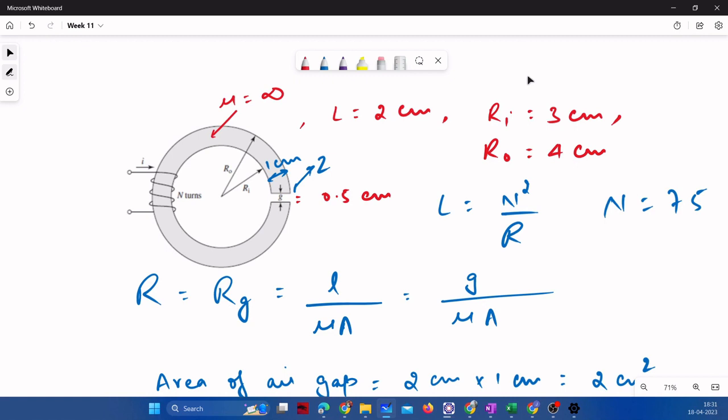Yes. And also the direction of flux should be a low reluctance path. You should always try to provide the high permeable path to the flux. So if you curl your finger in the direction of current with the number of turns, then your flux should not see the barriers, or it should not see the least reluctance towards the air. You might have heard the terms fringing flux and leakage fluxes. If those are high, then you are not utilizing your current and materials properly.